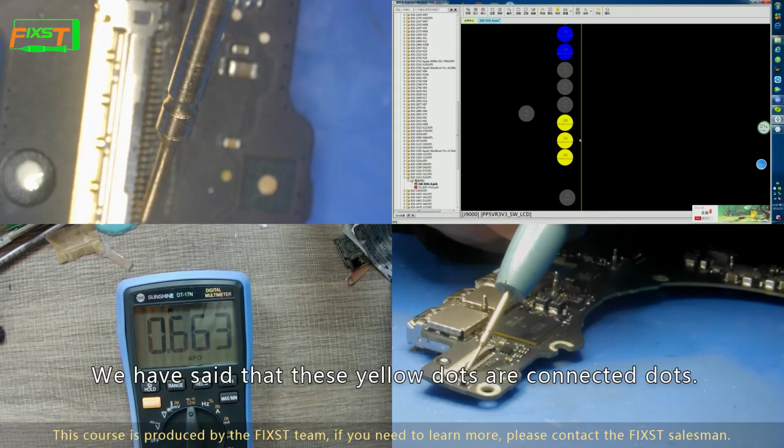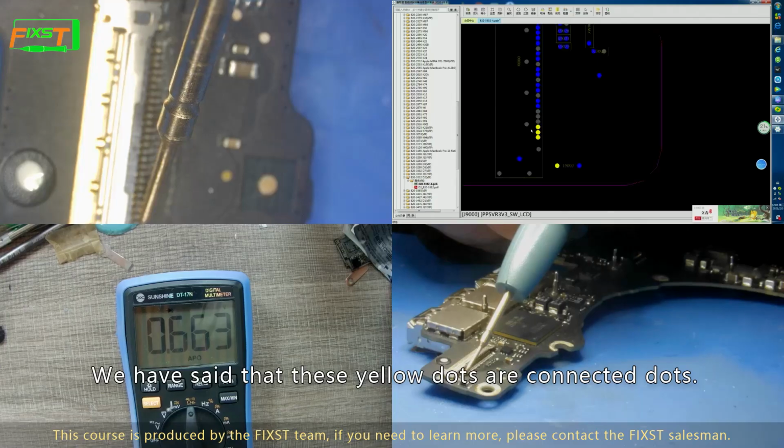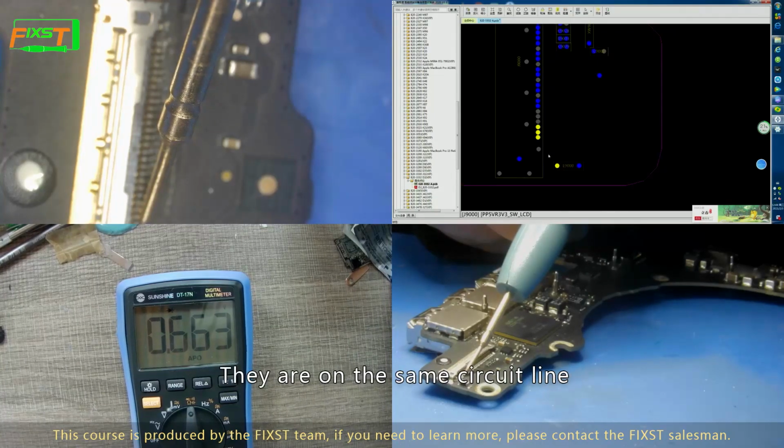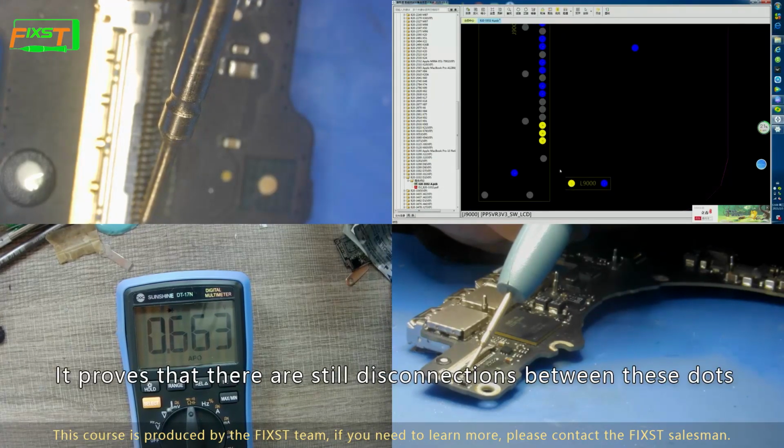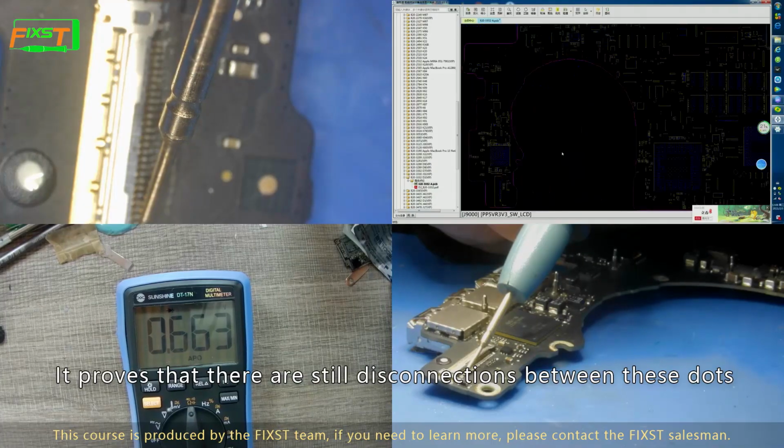we have said that these yellow dots are connected dots. They are on the same circuit line. Then if we measure this point, the value is OL. It proves that there is still a disconnection between these dots.